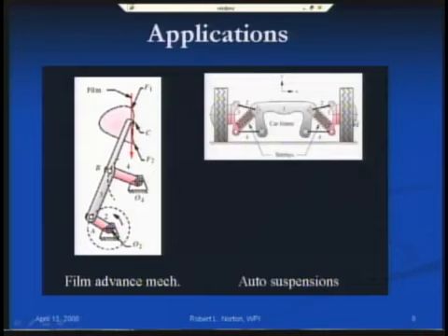Another very common application of coupler curves is automotive suspension. Here in a figure that's from your book, schematically depicts an automotive suspension system, could be front or rear. 4-bar linkage. Link 2 connects the wheel assembly, which is on link 3, the coupler, back to the chassis, as does link 4. These are typically non-Grashof. I don't think you want your wheels going around in circles in this plane at least.